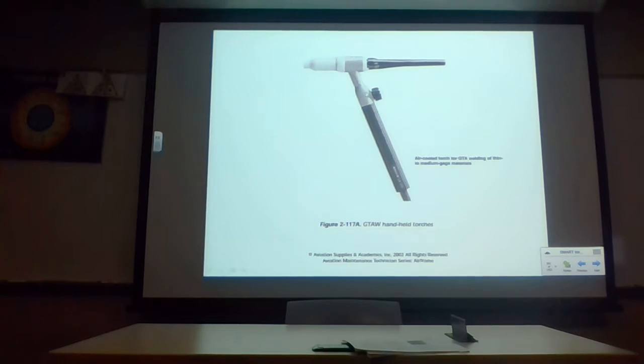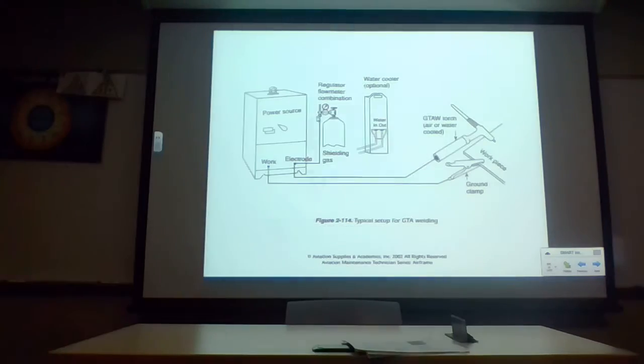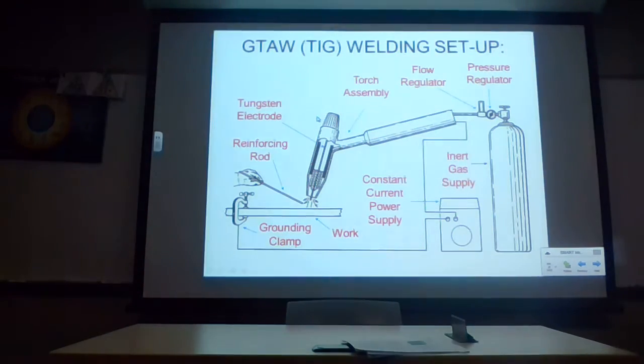Tungsten electrode, usually you've got a tungsten torch assembly. They've got a collet that's beneath this gas nozzle, and then they've got a collet assembly that pinches the electrode in place. And then when you screw the back half on, it pinches the collet onto the electrode so it doesn't back out. You've got maybe a better view of what it looks like. But you can see the collet here. You can see the tungsten electrode here. The collet grips the electrode. When you put the back half on, it pushes on the collet and squeezes it so that the electrode is held in position. That's how it's assembled.